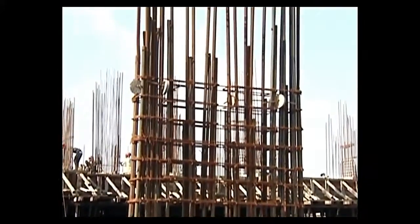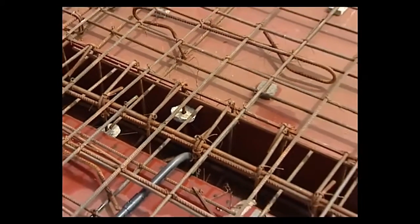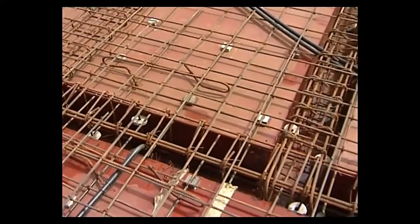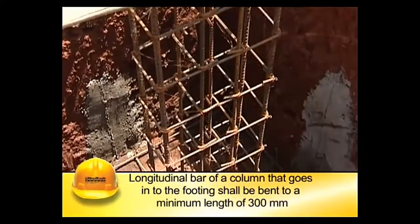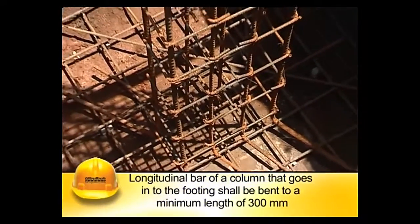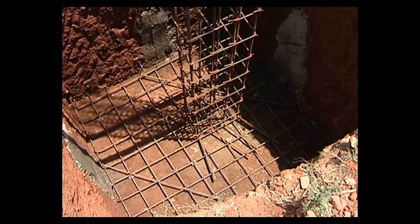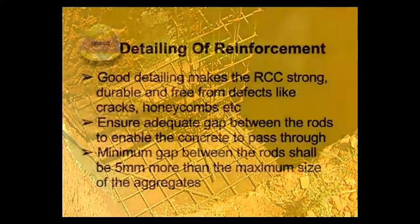Lapping can be done by tying the vertical rods with lap length as per design, or 2 rods can be welded to save on lap length. In columns and beams, the length of lap shall be as per design. The end of the longitudinal bar of a column that goes into the footing shall be bent to a minimum length of 300 mm to enable stability of the reinforcement cage till foundation is concreted.